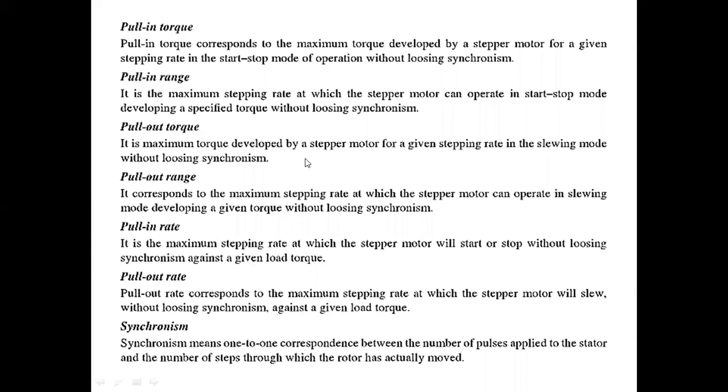Like that. Here, what the synchronism tells me is each and every time. Suppose we have six switches, S1 to S6: S1, S2, S3, S4, S5, S6. If you operate any one of the phases, suppose S1 is connected to the A phase, that is the A coil, and the A dash coil within the A phase is connected to, suppose, S4 or S5, whatever it may be.